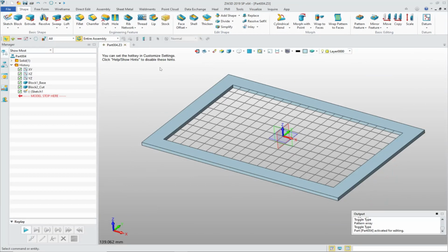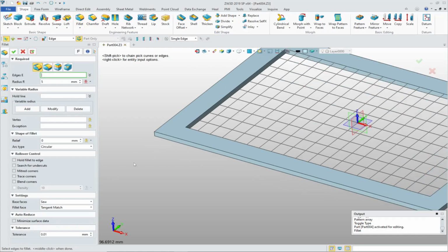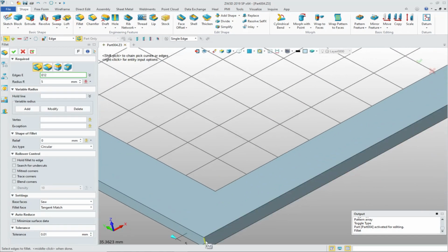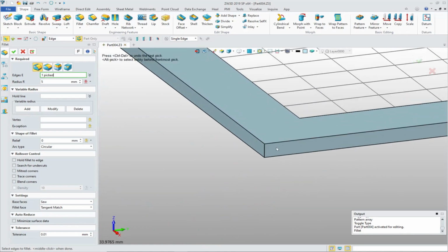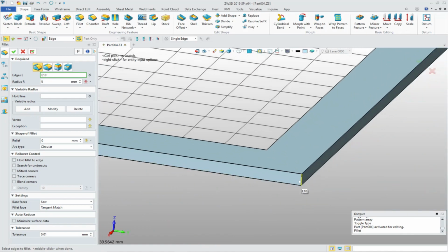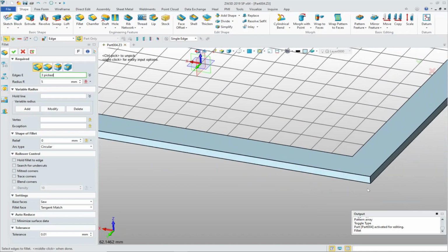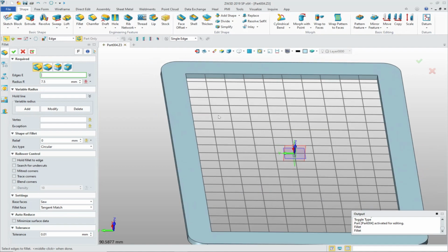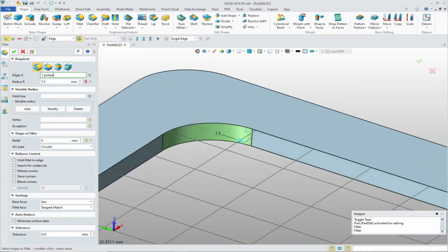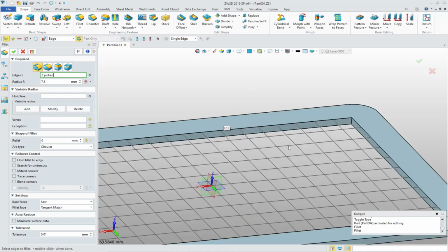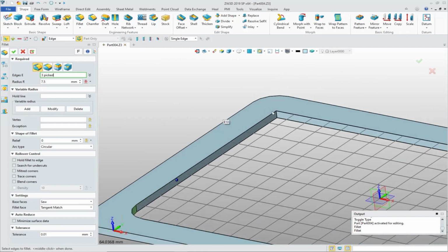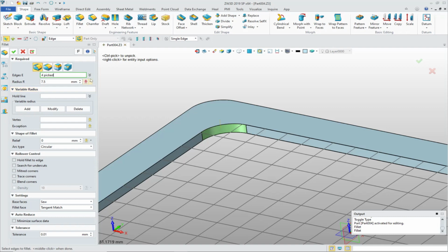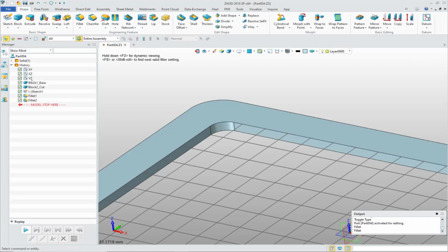So that's that sketch. So now I'm going to just simply go ahead and apply the fillet here on the outside corner, and that was a 7.5 millimeter fillet, 7.5, and middle mouse click to bring up the last used tool, click on the inside edges in succession and add those to that list here, and that was 4 millimeters if I remember that correctly.